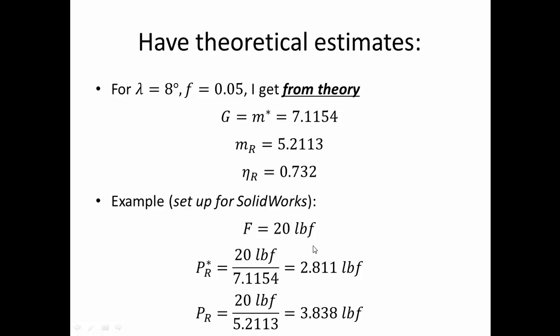And getting prepared for SolidWorks, I'm going to load my output with 20 pounds. So that means my theoretically best input would be 20 divided by 7.1154, or 2.811 pounds. The actual, with friction being considered, would be 20 divided by 5.2113, or 3.838 pounds.